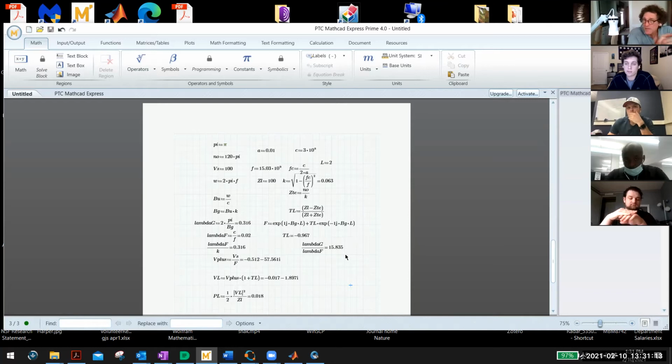Something I'm going to say, the quiz on Friday, God willing, will be on waveguides and waveguide-like problems like this. So I'll give you a few. You all see how this parallels exactly what you did with transmission lines. The only change is the length, I should say beta in the guide, right? That's the one thing. And the characteristic impedance changes with frequency in the TE10 mode. Got it? Any questions?